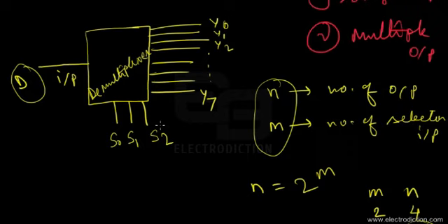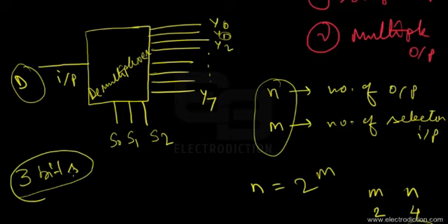So how do we select the required line? We select the required line by supplying an input binary code to the selector lines, and that input binary code would correspond to the decimal notation of the line, which is 1 over here. As we can see, the number of selector lines in this demultiplexer circuit is 3, so the highest number of binary bits it could hold is 3 bits maximum. So our selector input can hold a binary code of 3 bits maximum.